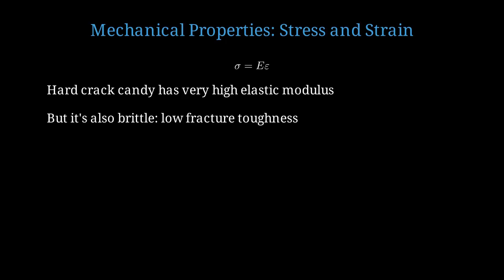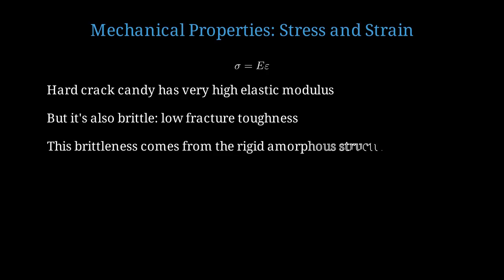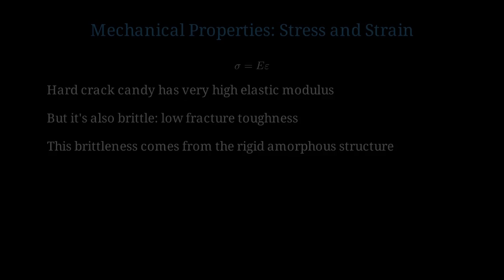Once a crack initiates, it propagates rapidly, causing the candy to shatter rather than deform plastically. This brittleness is a direct consequence of the rigid amorphous structure. Without crystalline planes that can slip, the material can't dissipate stress through plastic deformation.